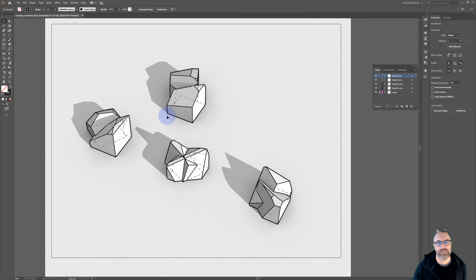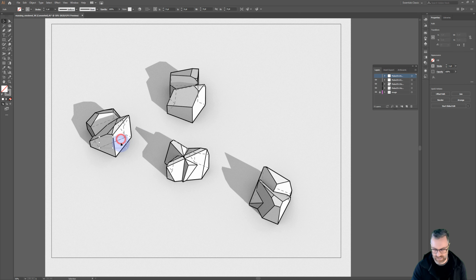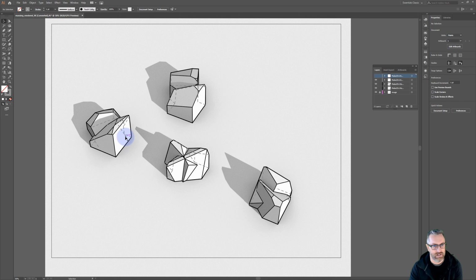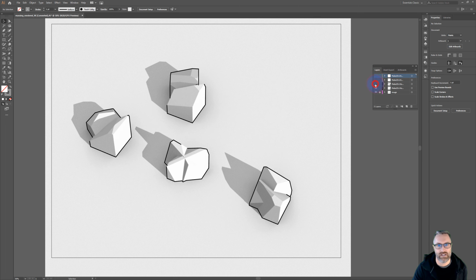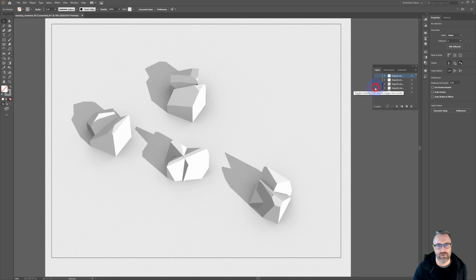And then what I would do is now play with the line weights a little bit. So you can figure out what's what. These are the tangent lines, which I actually don't want. And nor do I want it on this one over here. And so we can leave that one off. Our next one is our dashed lines. The next are the interior lines. And the last is our profile lines.